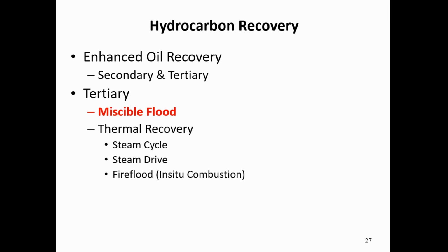So you can find that value in any guidance book to know what the MMP is. Make the injection pressure more than that MMP, and you will have good miscibility. You can achieve miscibility if you achieve the target of MMP.